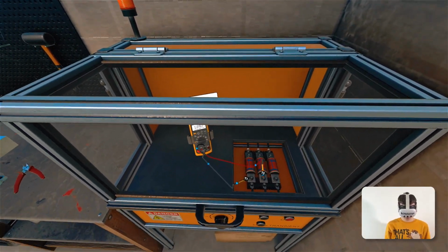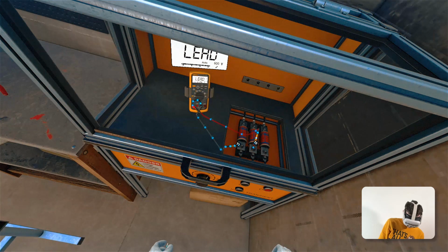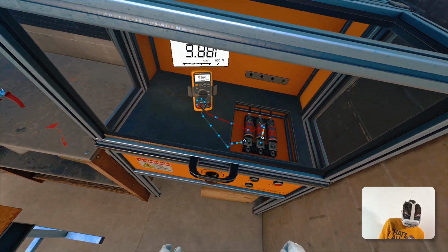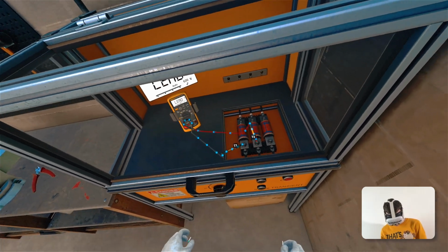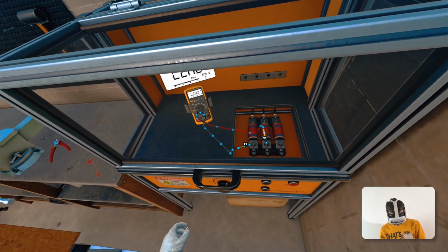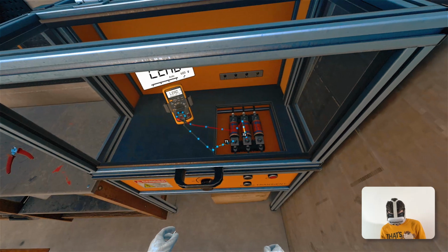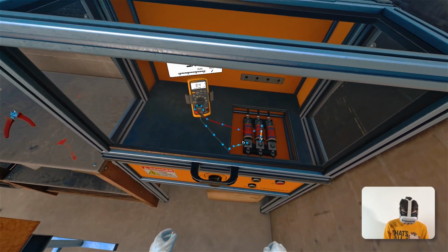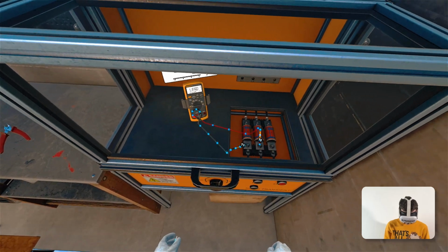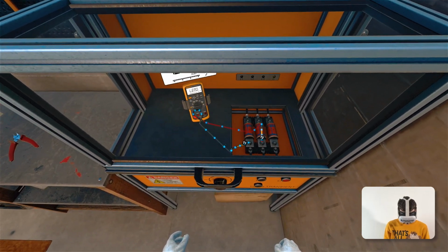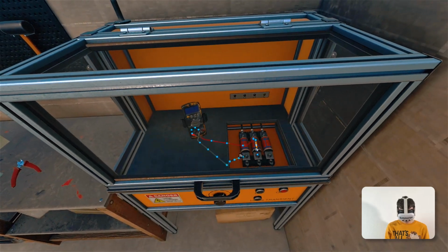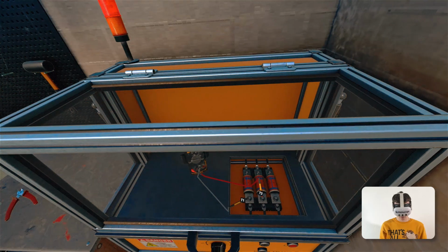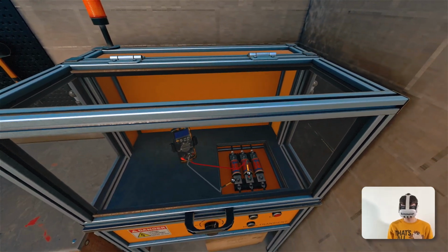When the power is turned on, the multimeter with inappropriately connected test leads creates a short circuit. This is because the multimeter is meant to be put in series with the circuit. A low impedance shunt inside the multimeter provides a path for the current to flow. As you can see, the multimeter is now providing a direct path for the current to flow from one electrical phase to another. This is a dangerous situation and can lead to severe consequences. And as the current continues to flow unchecked, it causes an arc blast inside the multimeter, leading to its catastrophic failure.